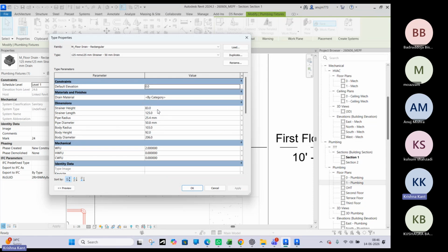But when you work on a high-rise building, in the plumbing there will be a pressure valve at every 7 to 8 floors, or sometimes 10 floors also. After the 10th floor, on each 10th floor, there is a pressure valve. Okay.